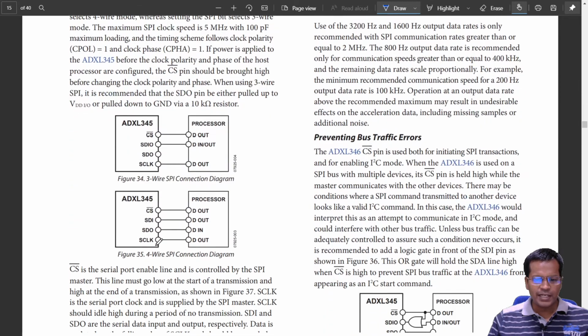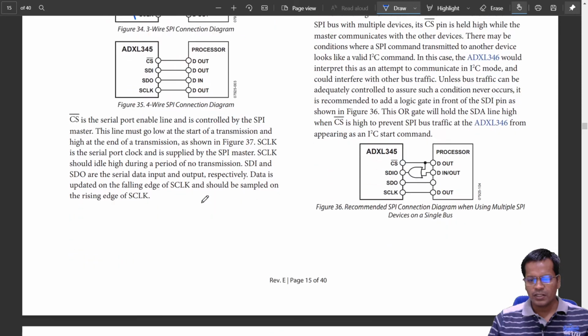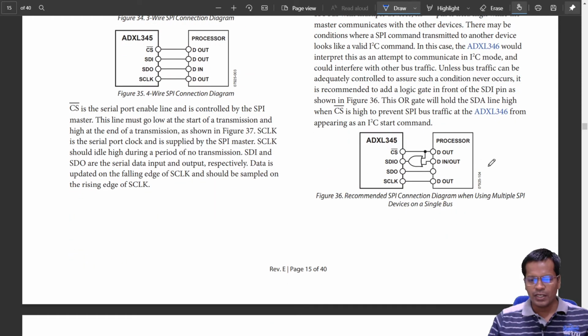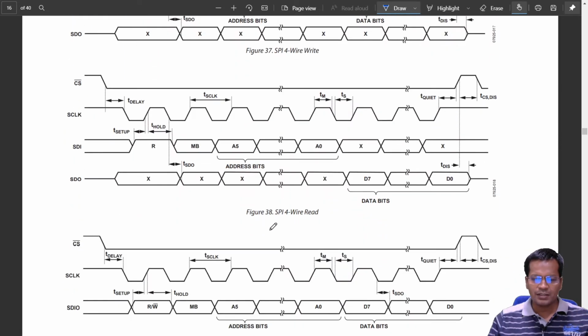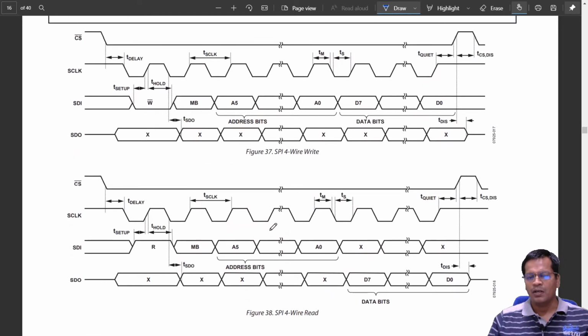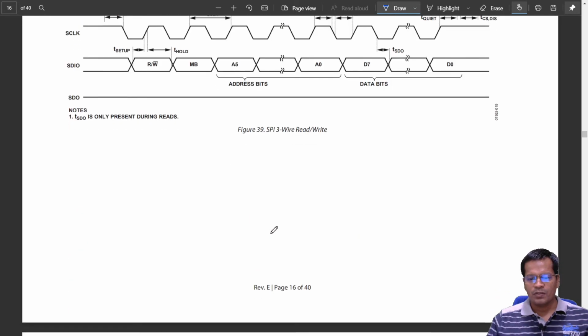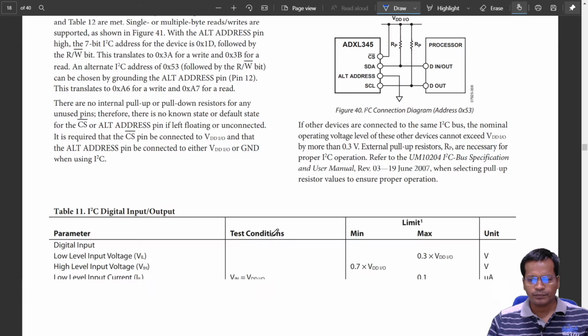So this is SPI communication, how that is to be done through a microprocessor or a controller. What all wires are of importance. This is how they are connected, how to select a chip and take the data out. There are electrical characteristics also, but nowadays these are prefed to a PC or a microcontroller. You don't go to that scratch level, they are for the designer now.